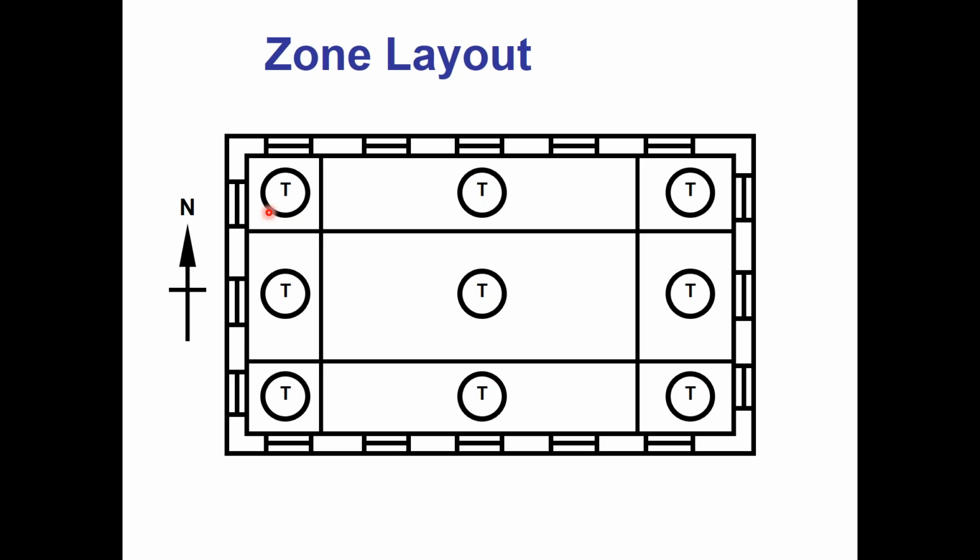But when I do that, I have to know in my head each time I'm making a compromise, right? Oh, I'm going to combine this guy over here with the rest of the north zones. Okay, fine. When I do that, I just have to know there's going to be a couple hours each morning that that person is not as comfortable as they otherwise would be, and they might complain about it. And depending on how important that person is, that may affect my decision.